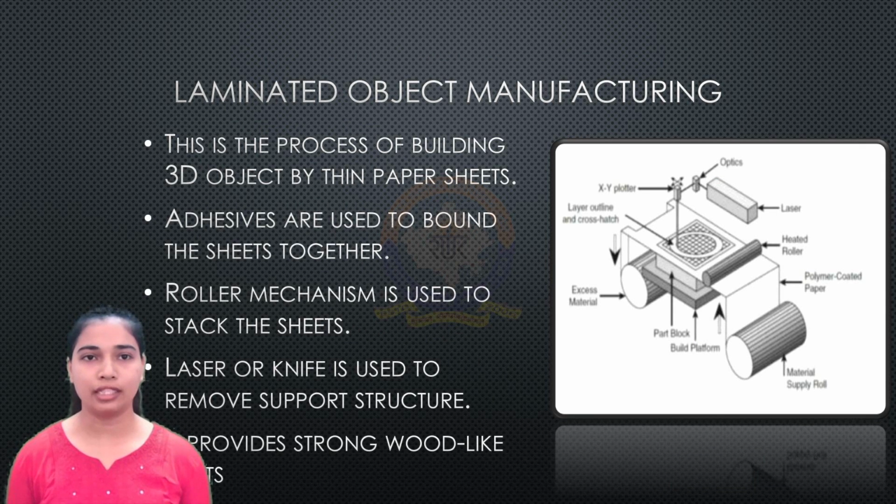This RP technology uses build material like paper, polymer, or metal laminated in the form of adhesive layers, which are fused together and then cut to the desired shape with a knife or a laser. A roller rolls on the build material, presses and melts the material adhesive. A microprocessor-controlled laser cutter is moved in XY coordinates to cut the layer on the basis of the virtual cross-sectional STL layer.